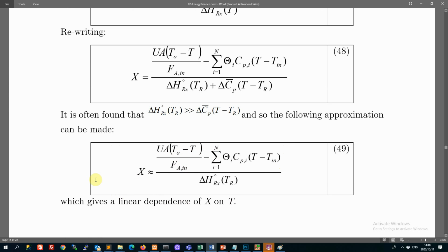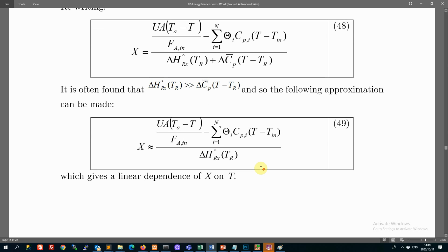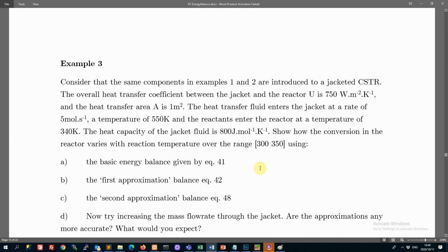Quite a lot of this can be applied to other reactors as well. And so again, we can start to think as chemical engineers, we are allowed to make nice approximations, clever approximations. That's what I should say, to credit us and make us sound good. But we can do it like that. And so anyway, that's the CSTR. That's a very good approximation to the energy balance. It's giving us a nice relationship between the conversion we achieve and the temperature in the reactor. So that's the energy balance for the CSTR.